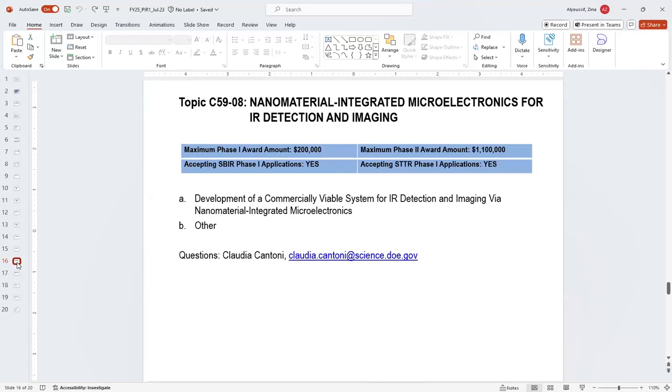So right now, the most common SWIR detectors and cameras utilize indium gallium arsenide for the photodiode layer, which has some inherent shortcomings, including dark noise count that requires cryogenic cooling, large pixel sizes, and complicated fabrication, which ultimately is expensive.